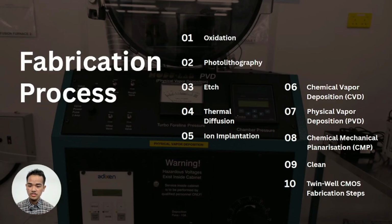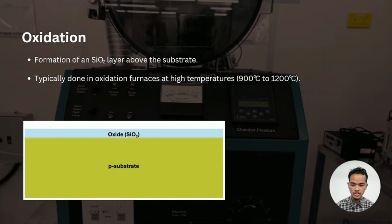Now, before we can get into the steps required to create a twin-well CMOS, it is important to know 9 of the most common processes involved in fabricating any modern IC. The first of which is oxidation. This simply involves growing a thin silicon dioxide layer above the substrate and is usually done in a high-temperature furnace.